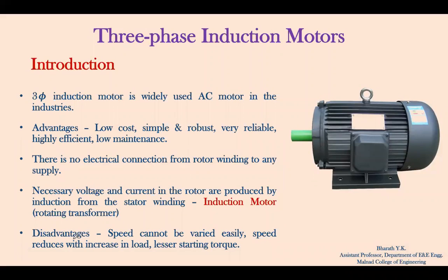In spite of all this, there are certain disadvantages, like the speed of the induction motors cannot be varied so easily. With the increase in the load, the speed drastically reduces. And compared to DC motors, the starting torque of induction motors is quite low.